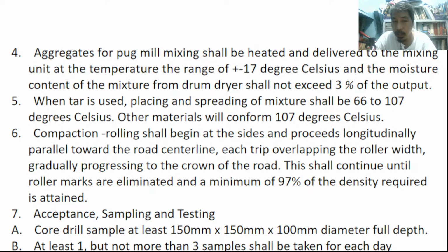If you have a cylindrical sample, the dimensions should be only height and diameter. That's enough. No need for three dimensions, because three dimensions are only for rectangular and cube-type materials. This sample is cylindrical because it has a diameter. It is confusing. Letter B, at least 1 but not more than 3 samples shall be taken for each day.